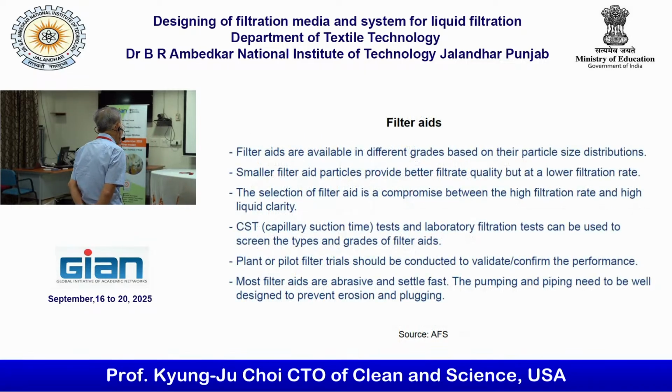Certainly, the filter aids are available in different grades. Even though diatomaceous earth is the same thing, there are so many different grades. Normally, the smaller the particle is, the better the filtrate quality, but the trouble is the rate is lower. Then how can you find out which one is better?